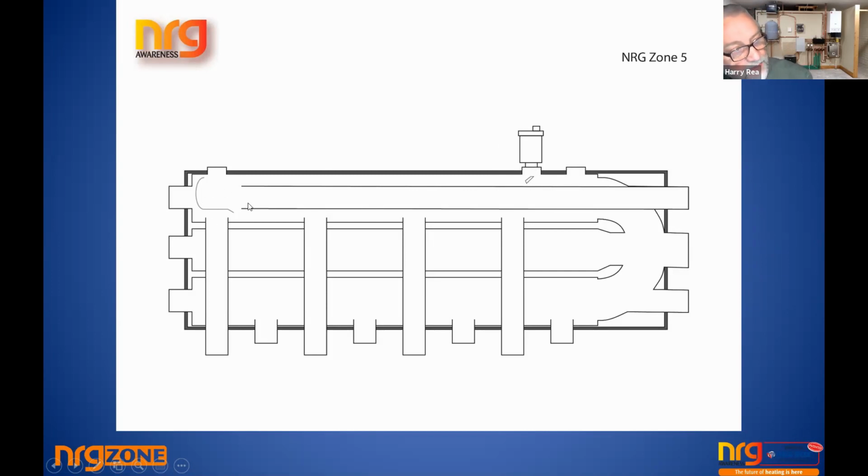Well, that's the reason why this baffle serves two functions. One is it prevents water from here going directly out and water from here going directly out, but it also plays a critical role in breaking up the water and causing deaeration. If you had an open system, this could be our expansion, but this is the most perfect place to put a cold feed, because you remember the idea of the expansion and the cold feed should be in close proximity to each other. Well, they're 75 mil apart. So you could take an open expansion for a system from here, and you could take a cold feed into here.